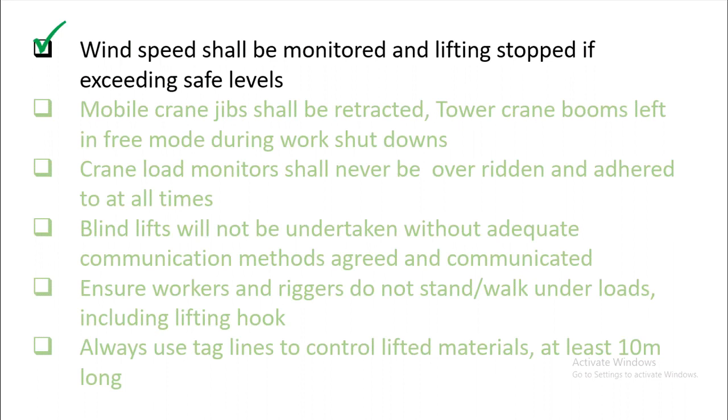For example, if you have 5 cranes on the site, you cannot rely on only one location to check the wind speed. So always check the maximum wind speed or safe operating speed of your crane, and also the maximum wind speed that legislation or regulations require, so that you are not violating the rules.